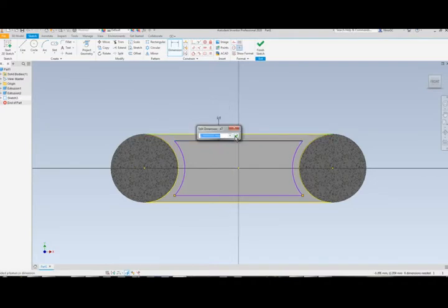Okay, so that is fine. But I also want to make this edge and this edge the same thing. So that's still going to be fine, but I don't want two competing dimensions. I want a parent-child relationship. So while this is still activated, I'm going to take my cursor and just click this number. What it's going to do is it's going to replace the 2.5 independent and place a D number. That D number indicates the variable's name.